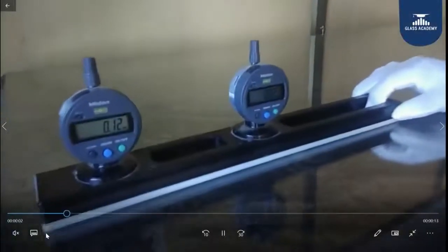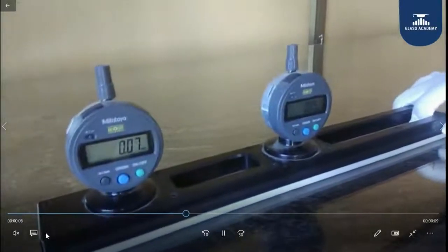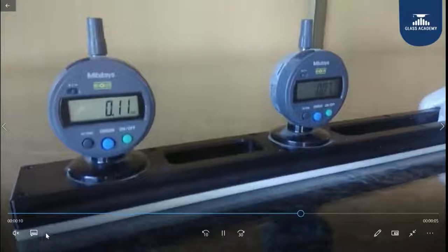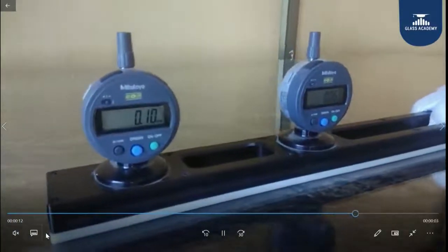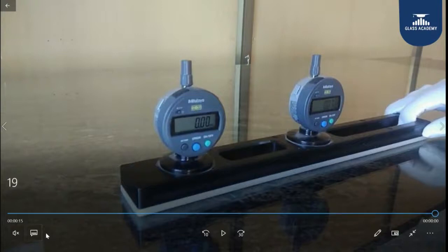If you see, I am taking a glass and I am making sure that as the glass is moving on the roller, the tin side, the bottom surface, will be in contact with the roller. So I need to place the bottom surface on top of the glass, and the measurement of the roller wave should be perpendicular to the direction of the glass. Generally we send the glass width parallel to the furnace.